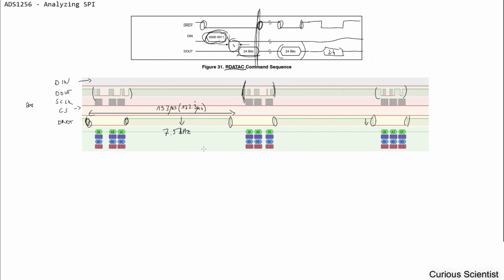And this is really good because if you can read the SPI, you can fine-tune your code and you can check for errors as well. So for example, you can see that your timing is not correct, or you can see that the data is not written to the registers that you want to read, and so on and so on. So this is a very useful device.